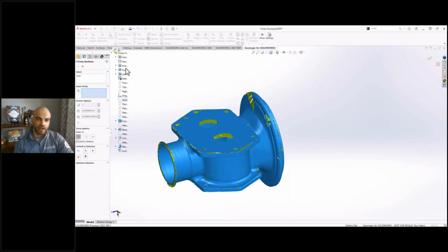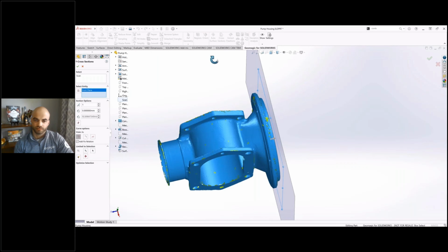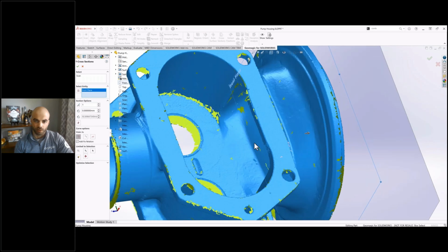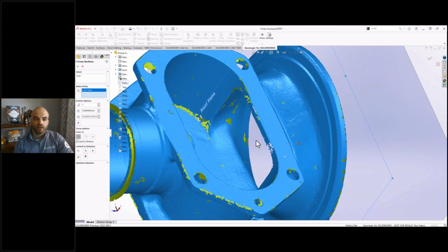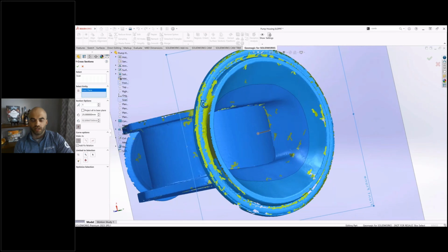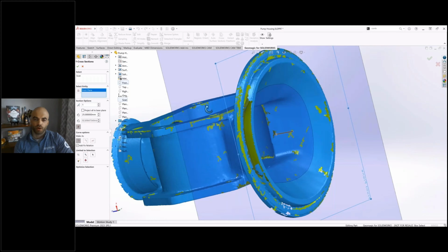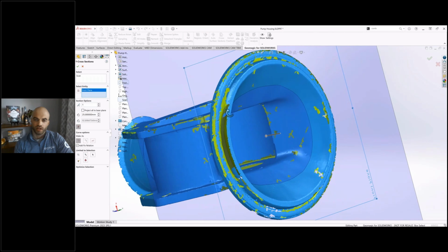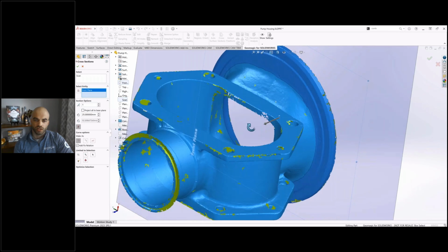So we're looking at modeling the inside of this horn geometry or funnel geometry on the end there. And we're going to work from the inside out. What I'm trying to do right here is drag this cross section. I'm trying to get it to line up to that innermost part of the loft, that sharp edge on the inside, in order to get as close to the scan data as possible.